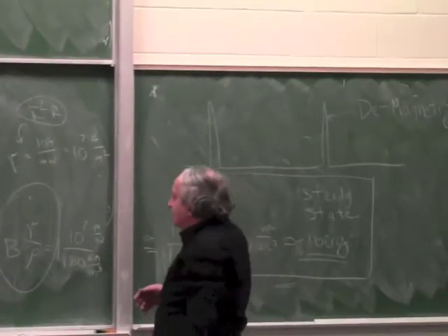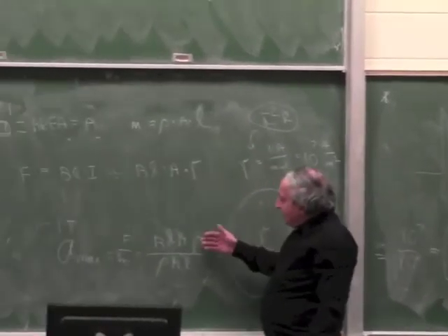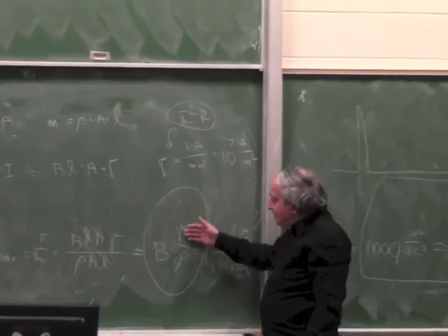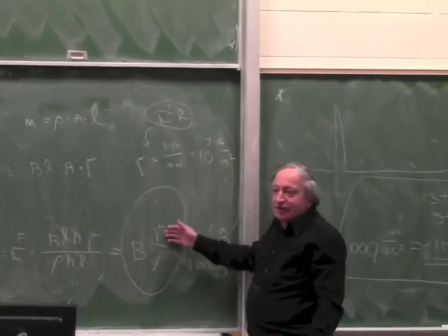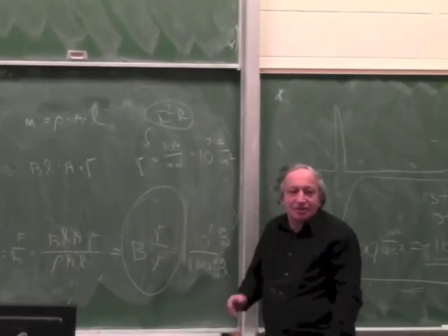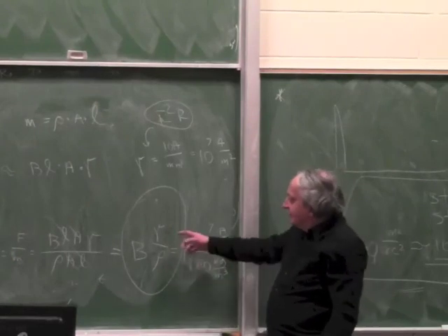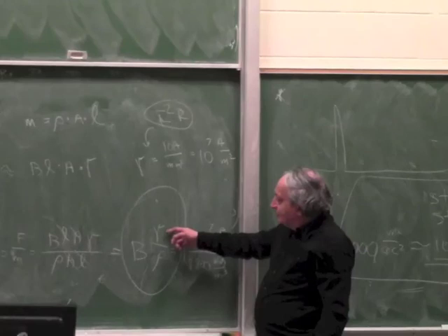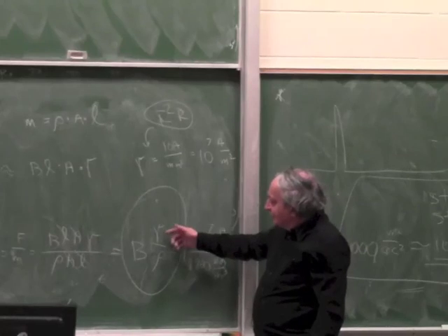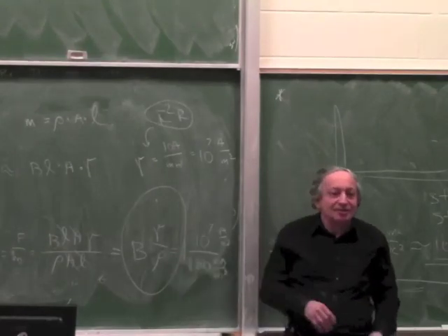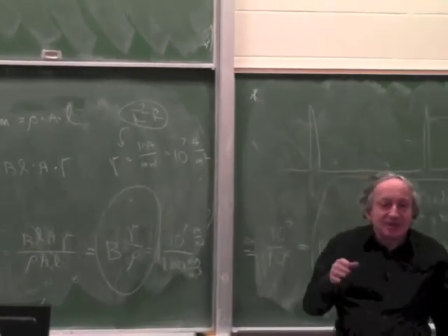So the ratio of current density to physical density for aluminum is much better than copper. Because this number is 0.6 roughly, and this number is 0.3 or even 0.5 and 0.3. So roughly it's almost double. Again, depending on the alloy and so on.